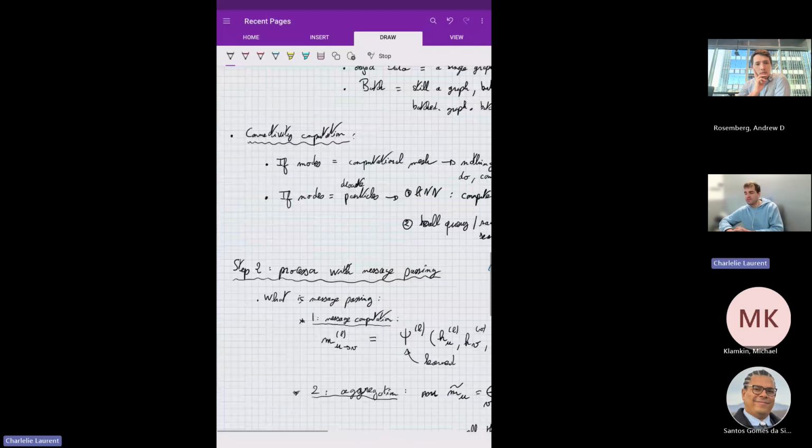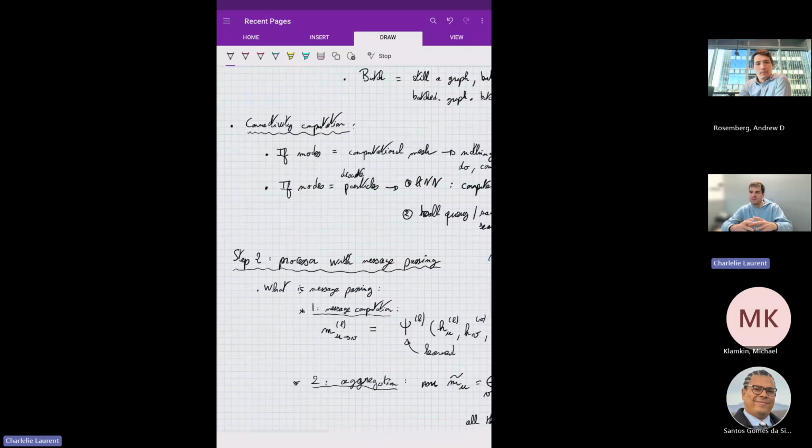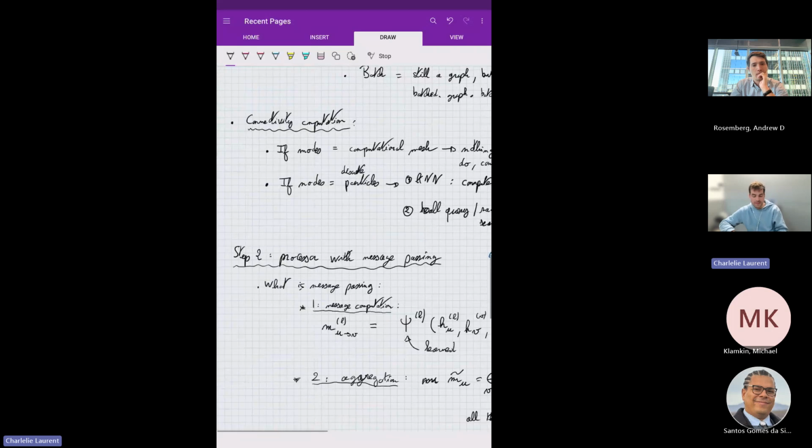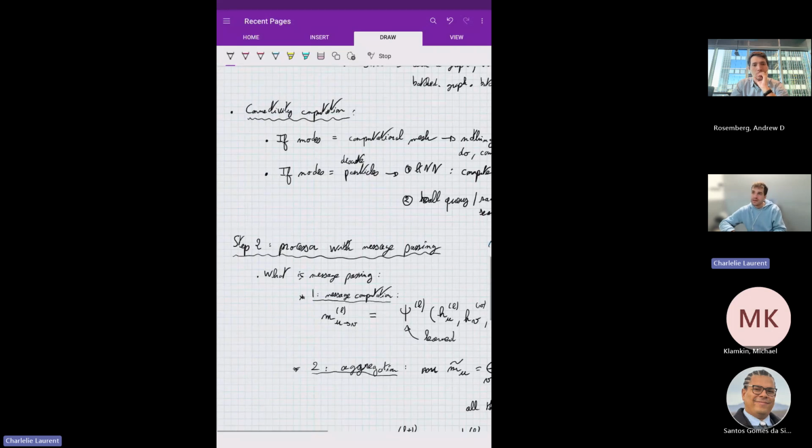If you do a convnet on those things, because a convnet takes the whole frame as input, or even an MLP, which takes the whole flattened image as an input, then in terms of training, the model has seen 10 samples, because those are 10 simulations. But from the point of view of a graph neural network, and in this case a MeshGraphNet, each node is a new sample. So in that case, the MeshGraphNet has seen 10,000 samples.